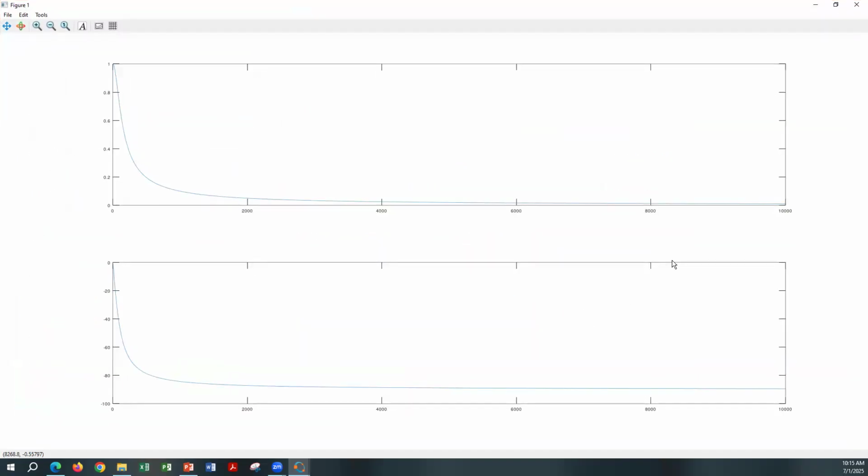So that's going to be your two plots. They don't look very nice, and there's a reason for that. What is the reason that they don't look very nice? Although the plots are correct, as you can see, it's a low pass, and it's going from 0 to negative 90 degrees. The range is quite large, because the cutoff frequency was simply 100 radian per second.